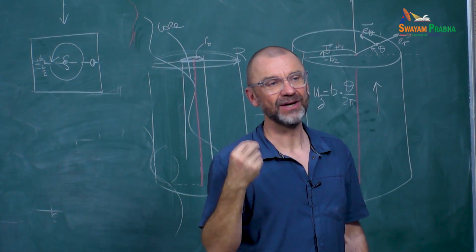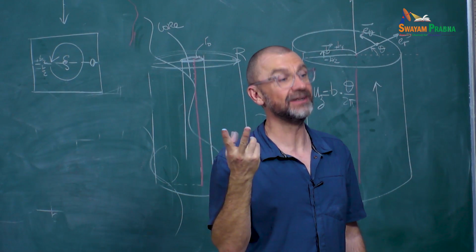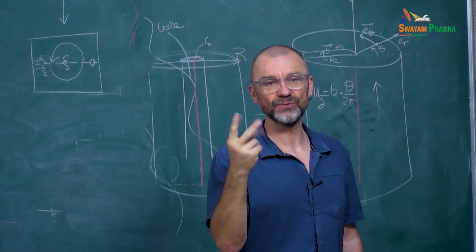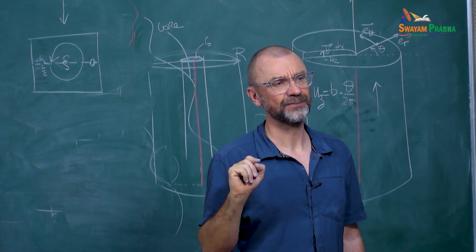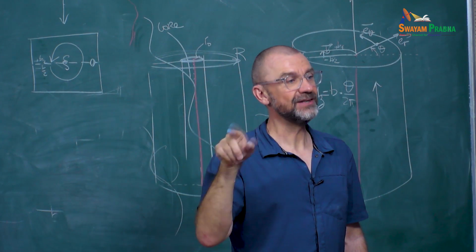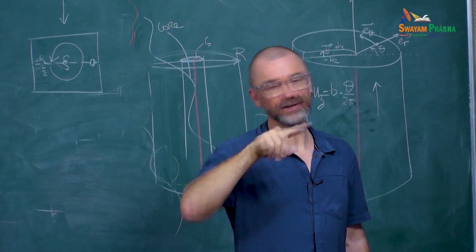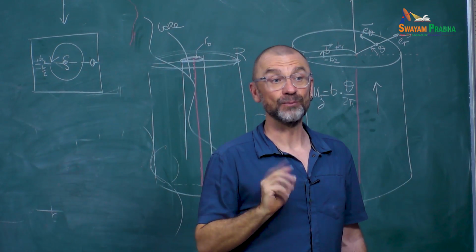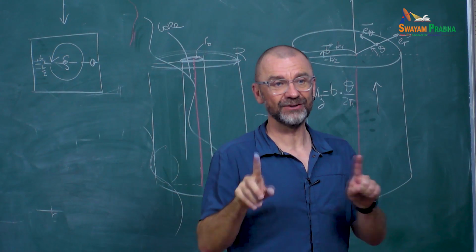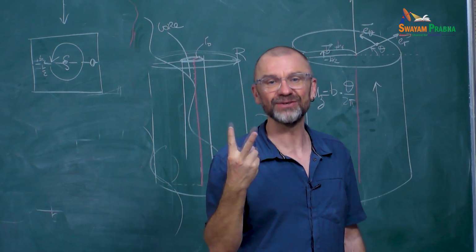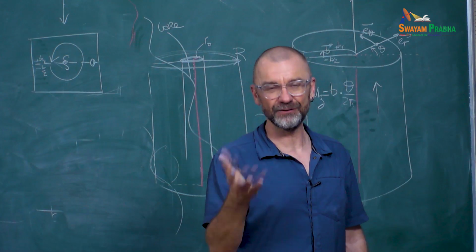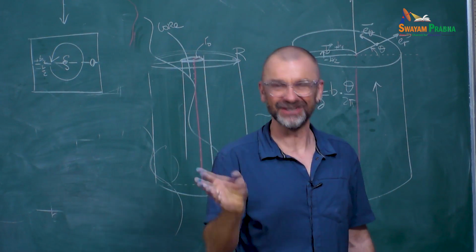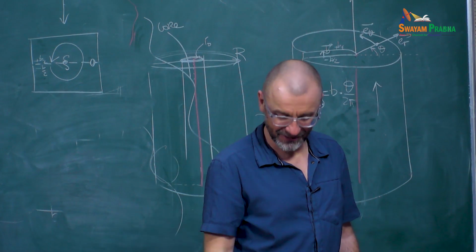What you do is you don't put one dislocation, it's a bit like a loop, but for infinite dislocations, you put 2 dislocations. You make a dislocation dipole. You create 2 dislocations with opposite Burgers vectors. Then the total Burgers vector is 0, and so you can apply periodic boundary conditions everywhere. The price to pay is that now in your simulation cell you have 2 dislocations. So basically you spend half of your time calculating something that you don't care about, because everything you care about is only on one dislocation and not on the other one. But that's the price to pay.